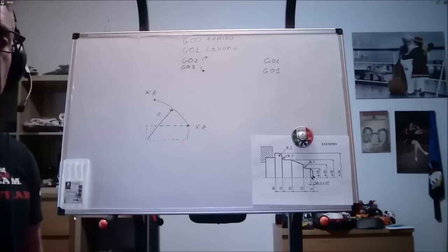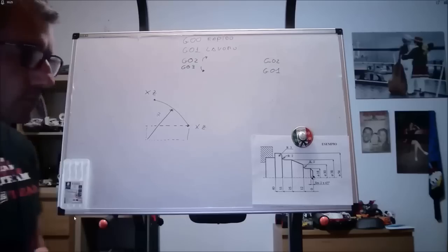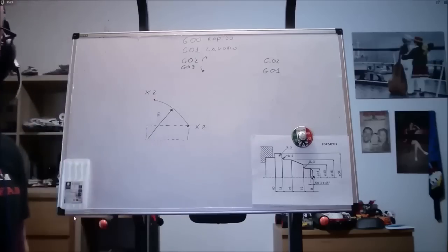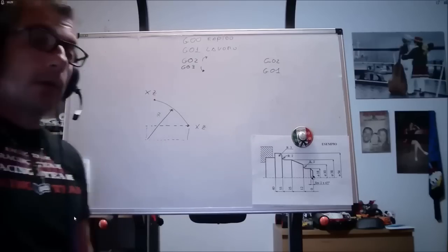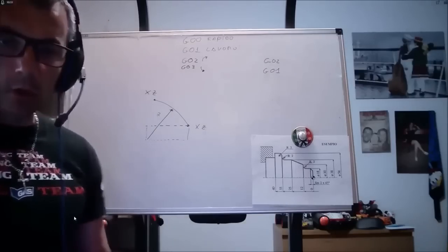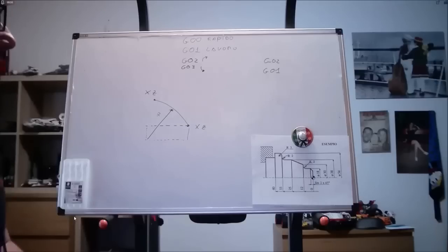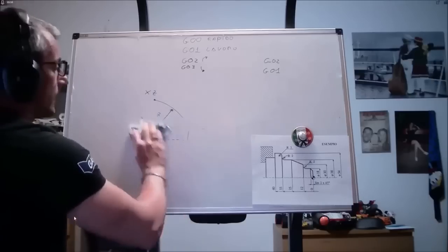Fortunately, it was a very advanced control and already used R. But know what I and K are, maybe. We will do some examples. Keep in mind that Fanuc still recognizes them very well. That is, you can program the arcs with R or with I and K.